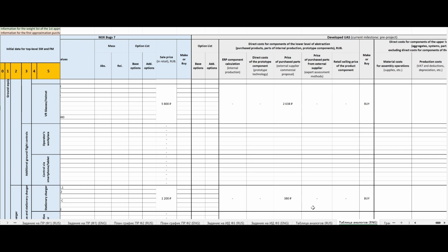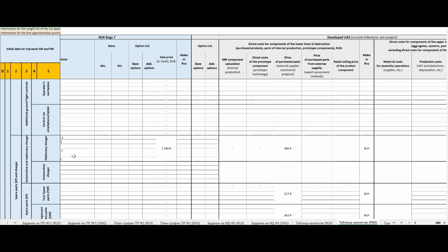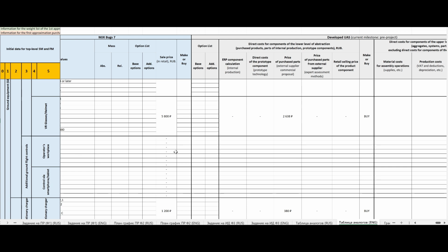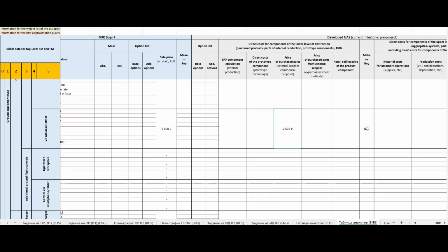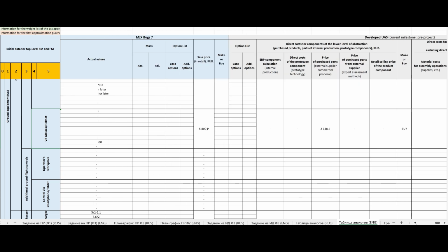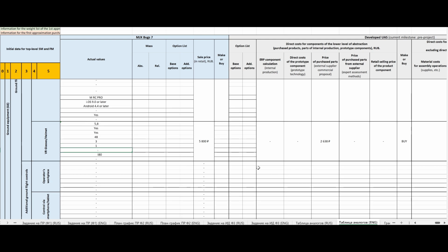If a helmet is included in the unmanned aircraft system, all the above-mentioned user functions are transferred to the FPV helmet interface. In addition, by switching to a helmet or FPV goggles, we are moving away from the video transmission range corresponding to clocked frequencies of Wi-Fi and moving to the freer 5.8 GHz band with the ability to select frequencies, which in most cases is not available for low-budget unmanned aircraft systems.